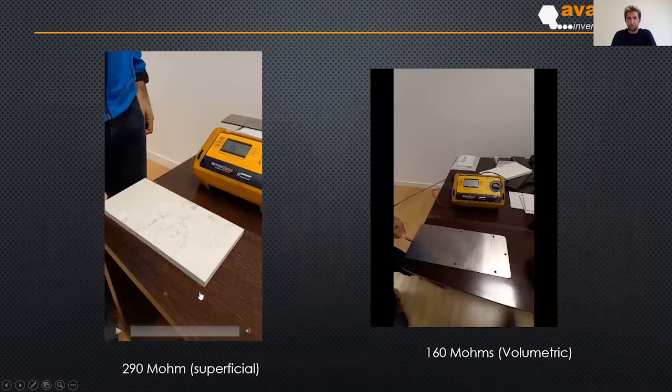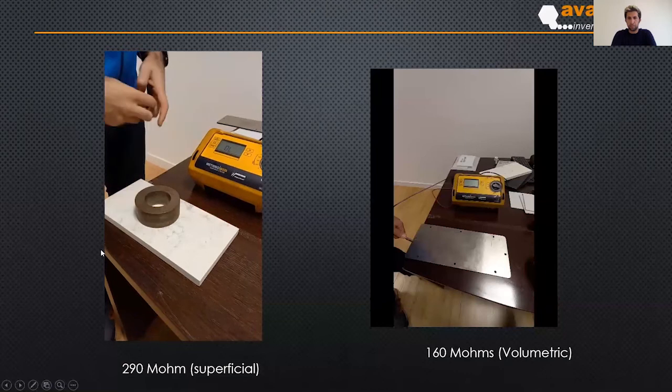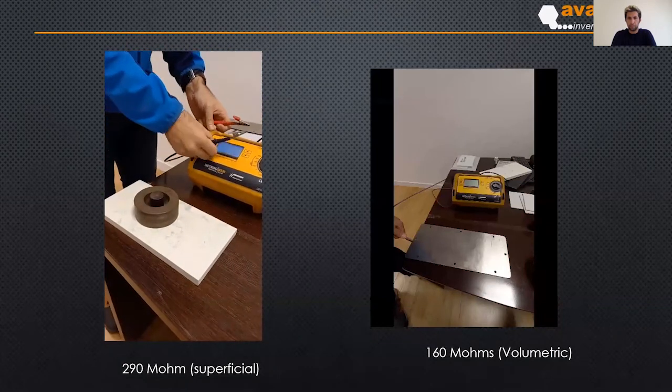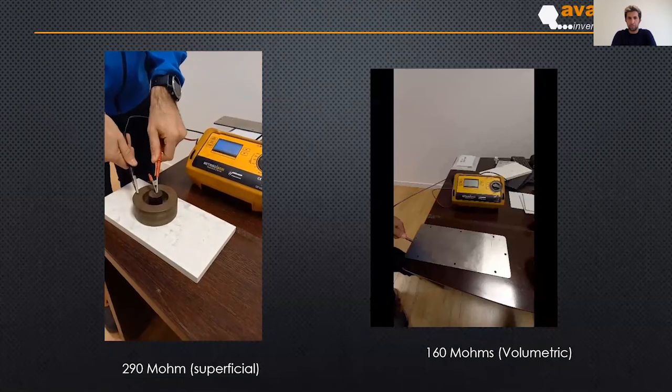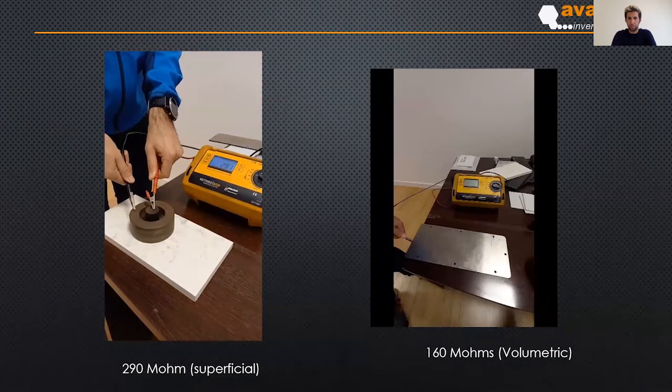Okay, this is another example with the same method, but in this case a tile of engineering stone, and we are going to make the measurement and see that the resistance is in the range of 300 megaohms, and antistatic in this case.